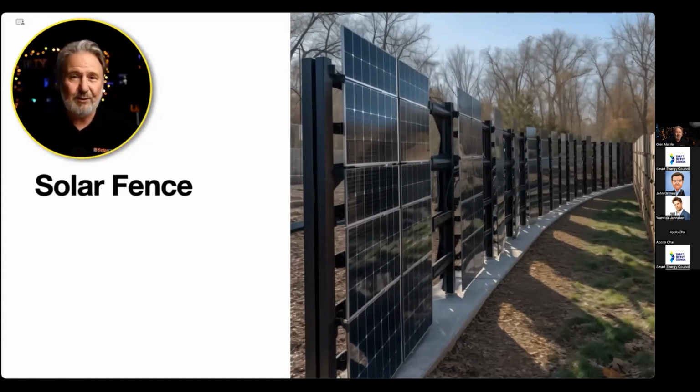Basically, up in the air on a roof is considered restricted access. But once you put panels at ground level, people can walk up to them and touch them. So you'd have to encase all of the cabling in a way to make it safe. Remember, it's likely to be an electrical system with hazardous voltages in those cables, so you'd need to protect them the same way that you would any AC wiring at that sort of location.